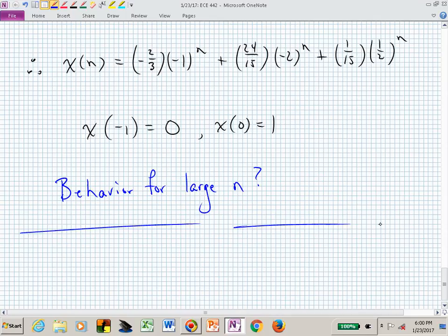Could we talk about a settling time for this particular x event? Does it ever settle? Even if we erased that middle of the three terms, does it ever settle? So if you had something that was bouncing around, sinusoidal, and it didn't decay, you couldn't talk about a settling time, could you? It's never going to a steady state. It just keeps ringing. It wouldn't make sense to talk about a settling time.